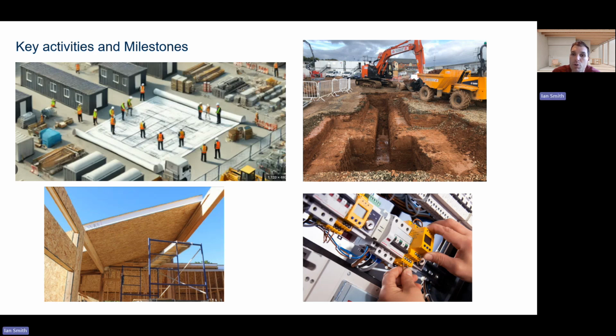Progress is monitored across the project using several methods. As a site manager, I will regularly compare the construction program with actual site progress to identify any delays or changes to the schedule. Weekly site meetings are also held with subcontractors and project managers to review completed tasks and plan upcoming activities. Site diaries are used, which will be highlighted later on, to record daily activities and labour levels and any issues affecting the programme. Visual inspections and progress photographs are also used to confirm that construction stages have been completed according to the schedule.